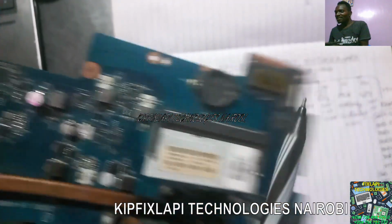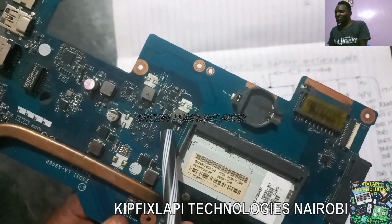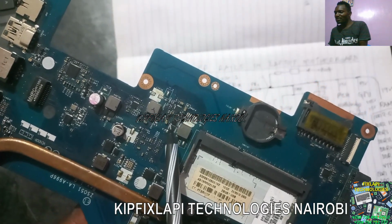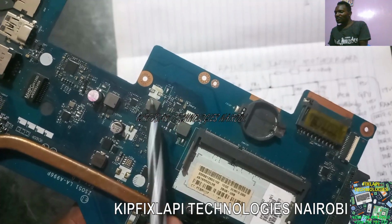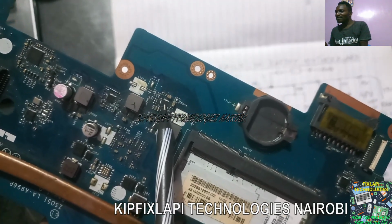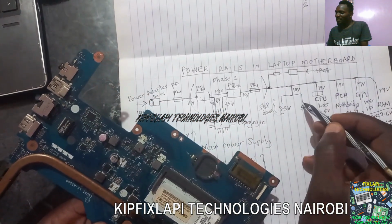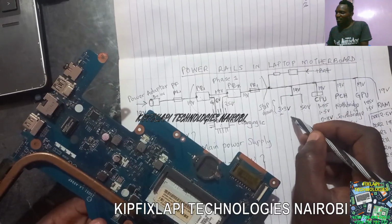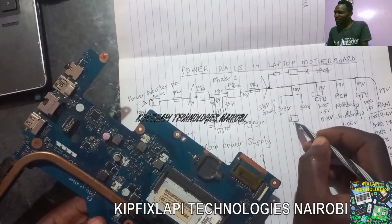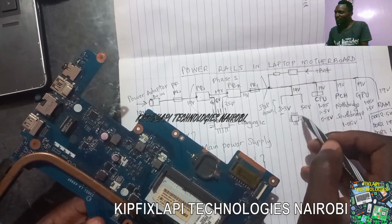I don't know whether they have capacitors at the back. I'm not seeing any, but they also should have the capacitors. So you can find the capacitors in both the power lines, these two circuits. Then they have this special IC, this one. So at this circuit for 3.3 and 5.0, you have a special IC there which is responsible for stepping down that power from 19 to the respective 3.3 and 5.0.